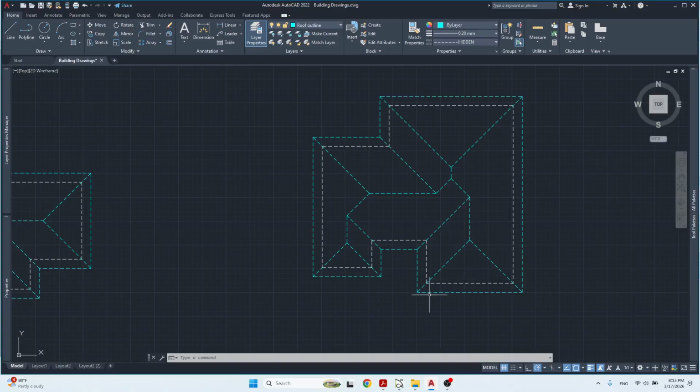And then from that, now I would do all of the different parts that stick out. I would put my hip rafters running, my ridge, and where this ridge meets this hip, I would just cut off the excess that I already had running down there.